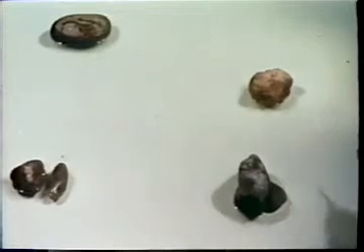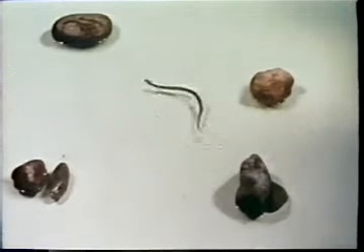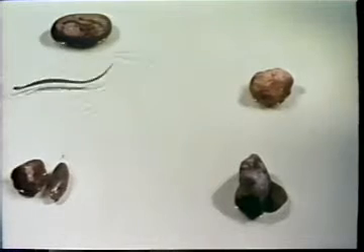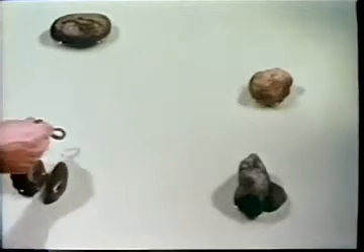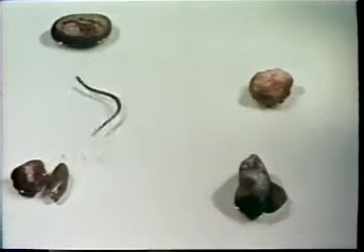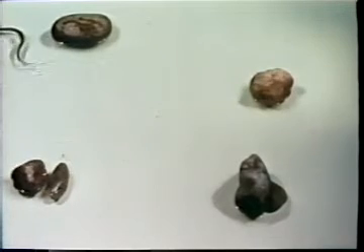Even a snake swims by moving its body so that each section of it is pushed forward by inertial reaction as the waves of bending move them obliquely in the water. All those we have seen have Reynolds numbers of order thousands or even millions. Microscopic creatures, which may have Reynolds numbers as low as 1/10,000, cannot derive any appreciable thrust from inertia. They rely on moving their bodies in such a way that they derive their thrust from viscous stresses.